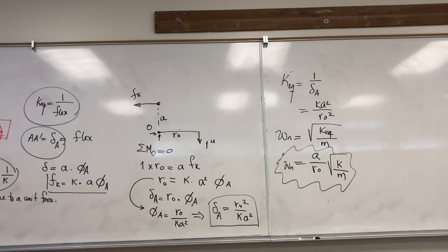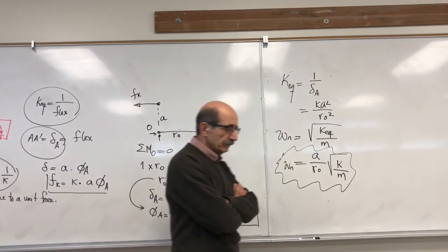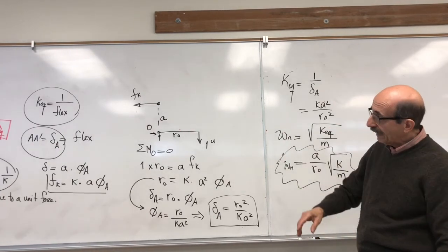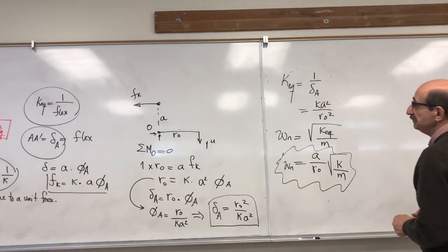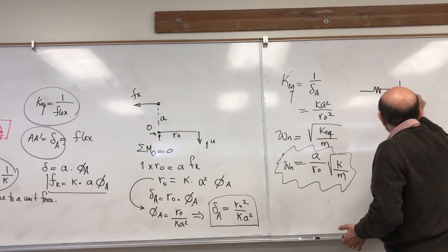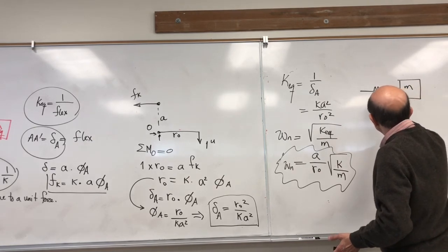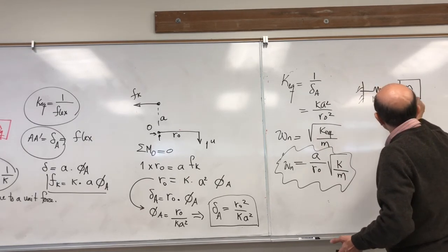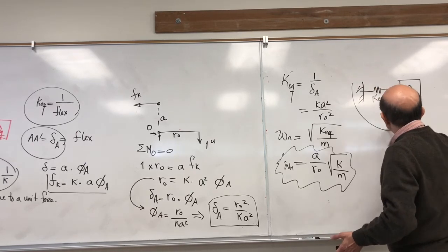So with a little bit of thinking, if you're given a problem, the essence of which is to find the equivalent stiffness in the system, you can use those, find the equivalent stiffness, and then having just one mass element which moves in a single direction, you can find the equivalent system. In other words, that ugly looking system, in terms of the vibratory motion, is nothing but this nice looking single degree of freedom system.